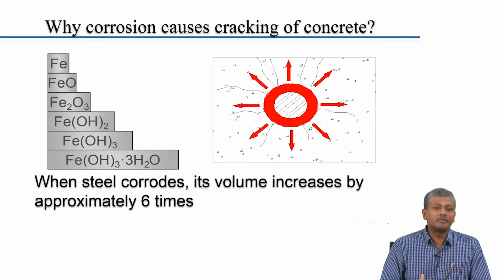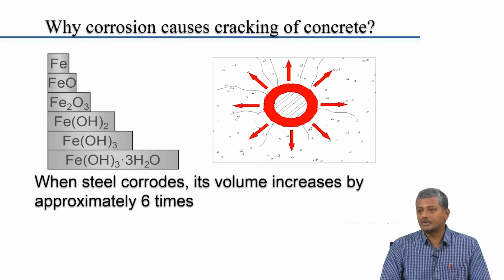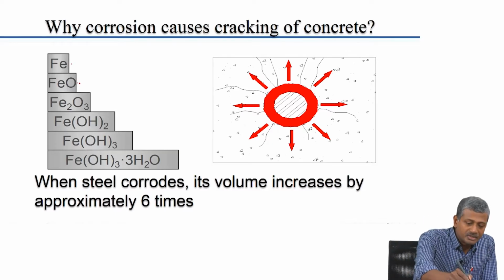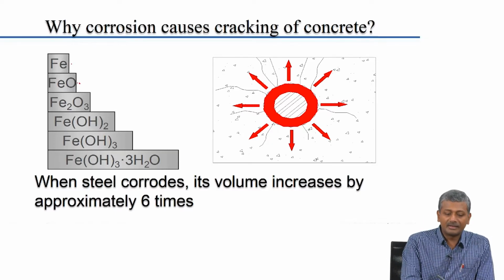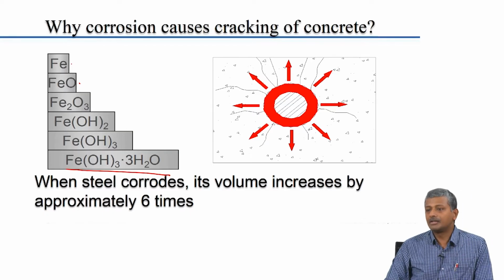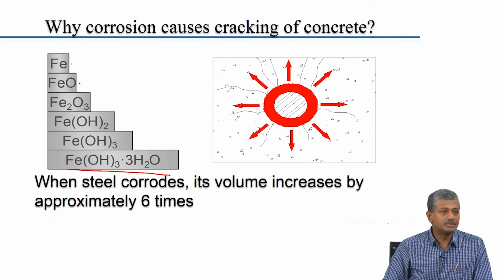You see that rebar is lying around in the open for days without being used, and because of that it develops a mill scale on top, right? And that scale is usually a problem, not really a good thing. Now, obviously when rebar gets converted to its oxide or hydroxide forms, there is a change in volume associated with that process. When iron changes to iron oxide, there is a slight increase in volume, but the hydroxides are the ones which have a very large volume as compared to the original steel.